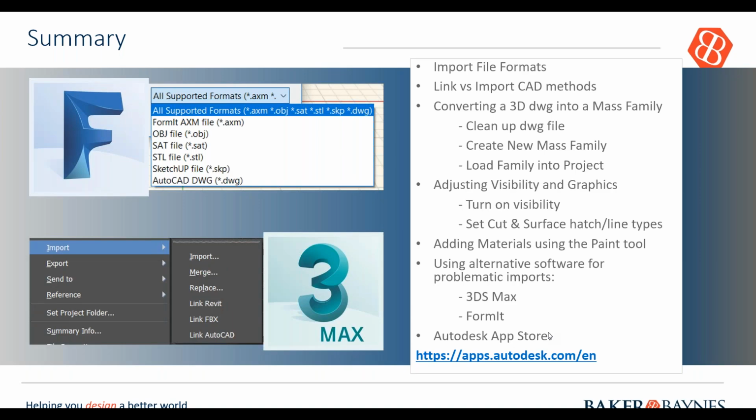All right, so I'm just going to quickly go through a summary of what we've done. We went through some of the Revit import file formats, then what linking in a CAD versus importing CAD is, and then how to convert a 3D DWG into a mass family. First we cleaned up the DWG file, created a new mass off of the family templates that we have, then brought the DWG into that mass family, and then loaded that family into our project.